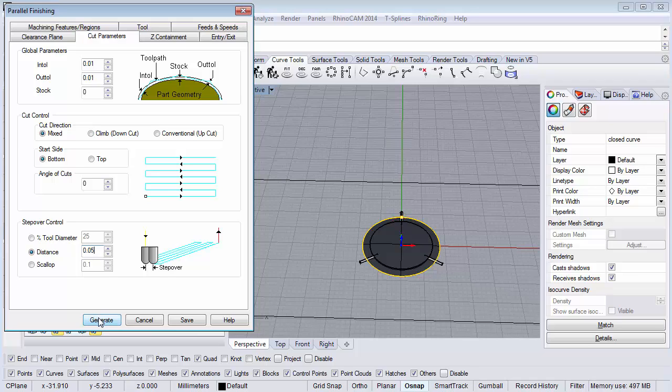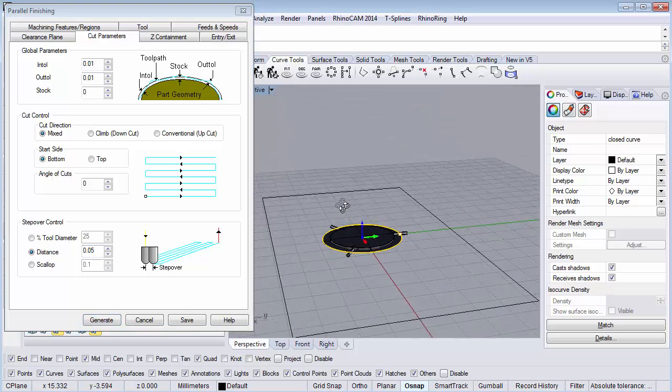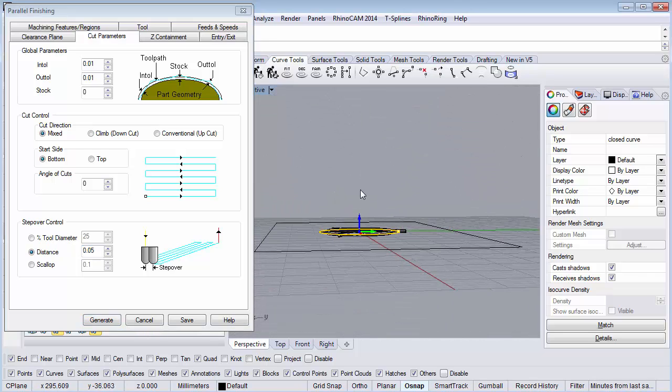Now what you want, and this is what Mr. Perth was asking about, is when it's finished cutting this and you're going to instruct the machine to roll, think about it in your mind's eye. The last thing the cutter does is come down, busy cutting, and now the cutter's point is down on the wax. Then we tell the rotary to roll this thing around because I want to cut the other side, but your cutter is still down here, so when it starts rolling, you're shoving a big piece of wax into the cutter.